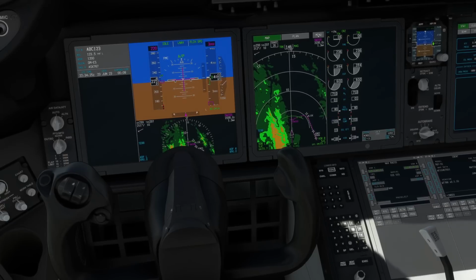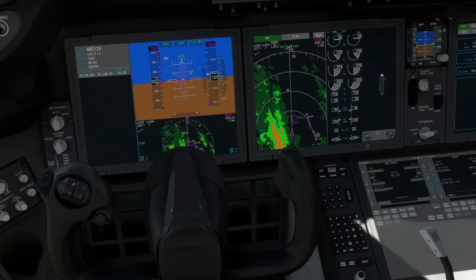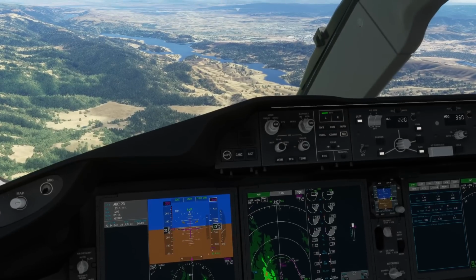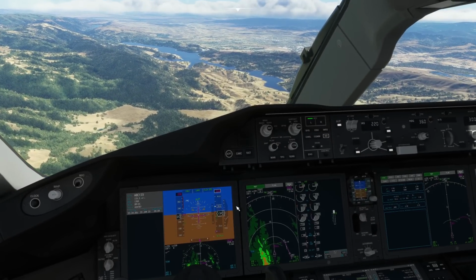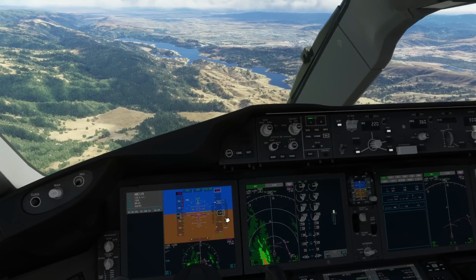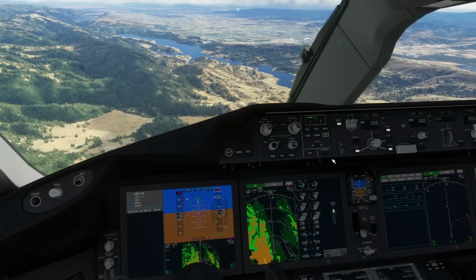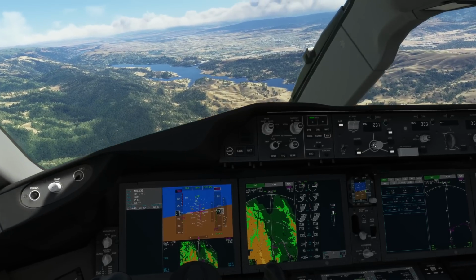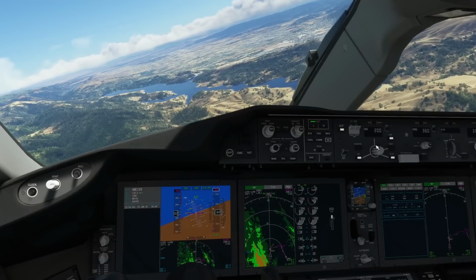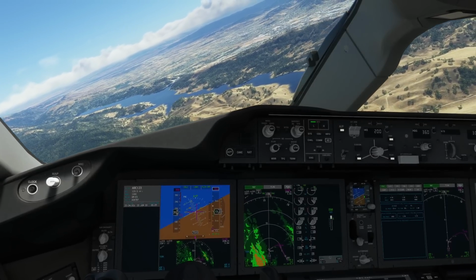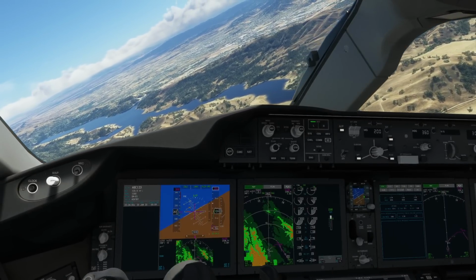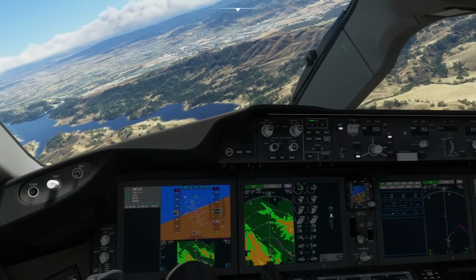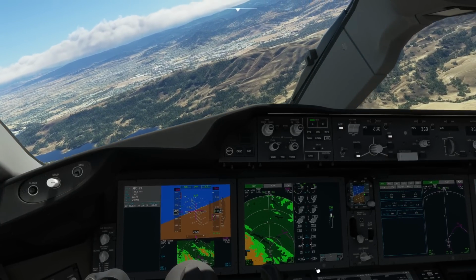So we're going to go back to first stage of flaps, which will help us make the corner without stalling at these speeds. Getting lower and lower. We're coming down towards 3,000 feet though, which is good. So we get the gear down as well. We'll slow down a bit further to 200 knots, 225. We use the spoilers to make that happen. So if we zoom back in here, this is really nice, isn't it? The way the displays work.